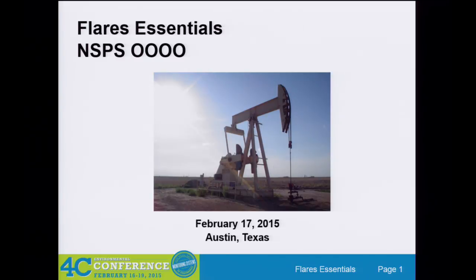Until the DMAT tool or things like it that we're familiar with, if you've been part of that in the environmental world, most of the time the operators never knew what valves were open to the flare because they're not a control valve. They've got a knockout pot that was giving them problems, and they open up the manual valve to the flare, and 3 days later it's still open.